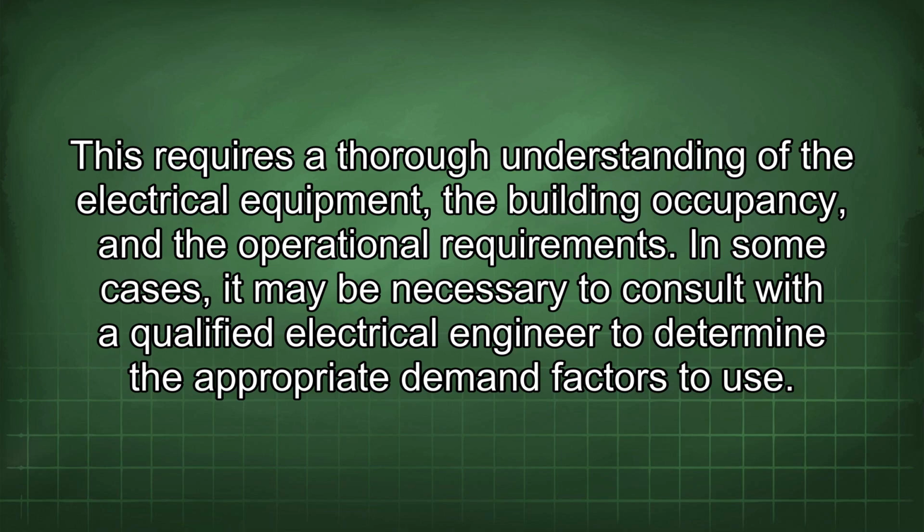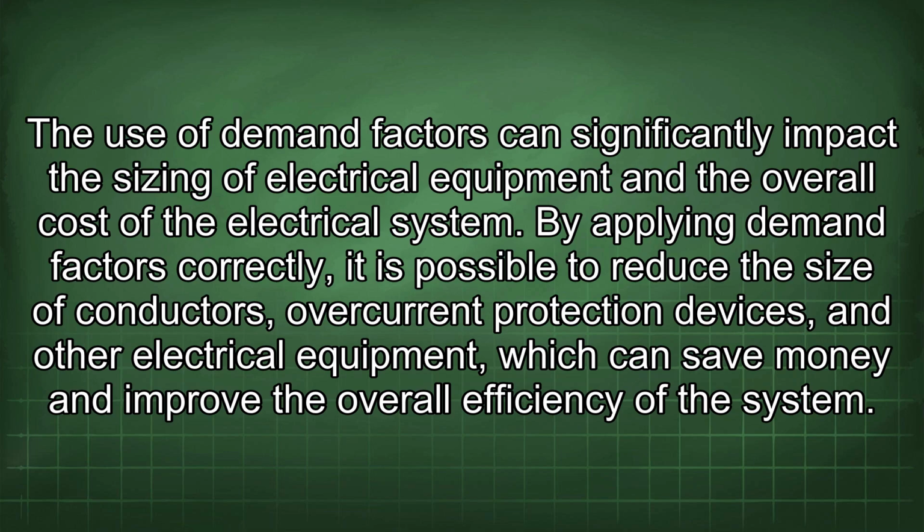The use of demand factors can significantly impact the sizing of electrical equipment and the overall cost of the electrical system. By applying demand factors correctly, it is possible to reduce the size of conductors, overcurrent protection devices, and other electrical equipment, which can save money and improve the overall efficiency of the system.